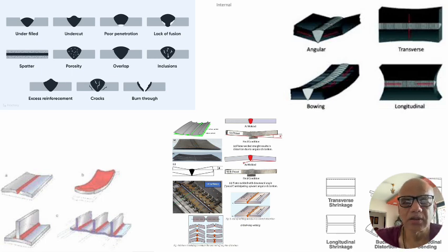That means the excessive current has melted material more in the last layer because you are in a hurry to finish and go. But it has not actually melted the parent metal which is required. The parent metal has to also melt to have a proper bond or a fusion. If that doesn't happen, overlap is not good. Otherwise, having 1.2 millimeter overlap on each side is a desired welding practice, and one should have it.